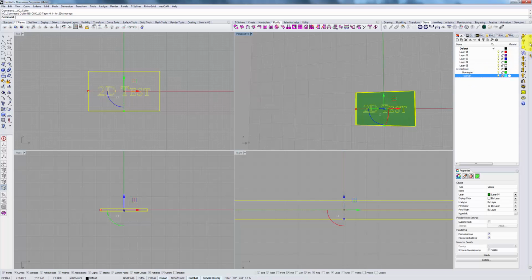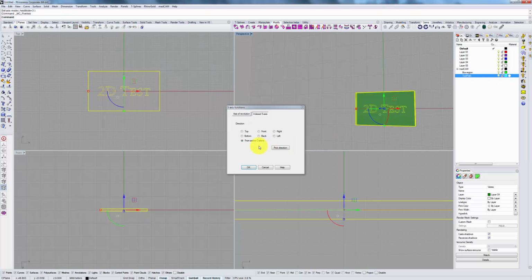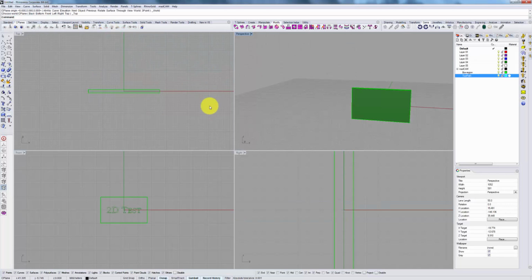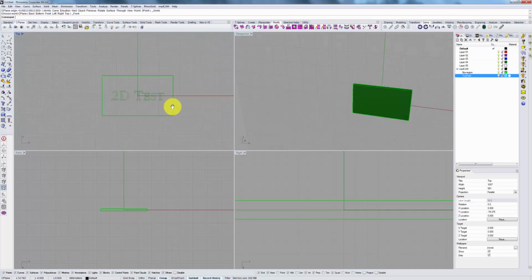Now make sure you're in the 5-axis tab, click our 5-axis option, and make sure that the active plane is selected. If it's not, you might get incorrect results. And to make sure that we're cutting from the right direction, you have to examine our top view. Top view is how your cutter will see the model beneath it. So it's sort of like looking from top down. If you see this sort of a picture, then you're in the correct position. If you see something different like this, you're not in the right position. So make sure you find the right C-plane for your cutting.